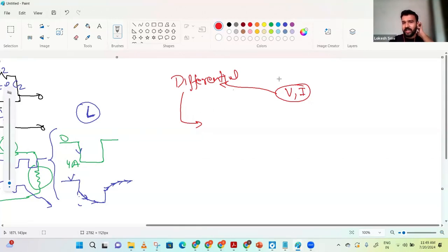So RC modeling helps us convert the model into differential equations. That helps us understand the limits of the system in the frequency domain, and that gives us better clarity in terms of what sort of action should be taken when we develop algorithms. So, single sentence answer: we use the RC model mostly when we are developing algorithms, like SOC algorithm, SOE algorithm, SOH algorithm. For these algorithms, RC modeling is very important, because before implementing them, it helps us understand the behavior of the system in the frequency domain.